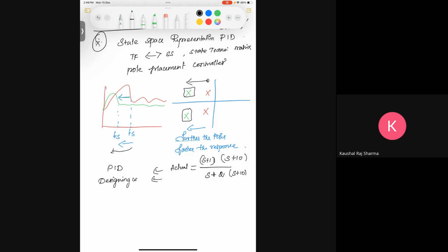So far we have been doing all this same work, but in different aspects, using different kinds of tools. Just in the PID controller we would have tuned this KP, KI, KD, ultimately changing the roots or changing the pole location, so that I will get the desired response.